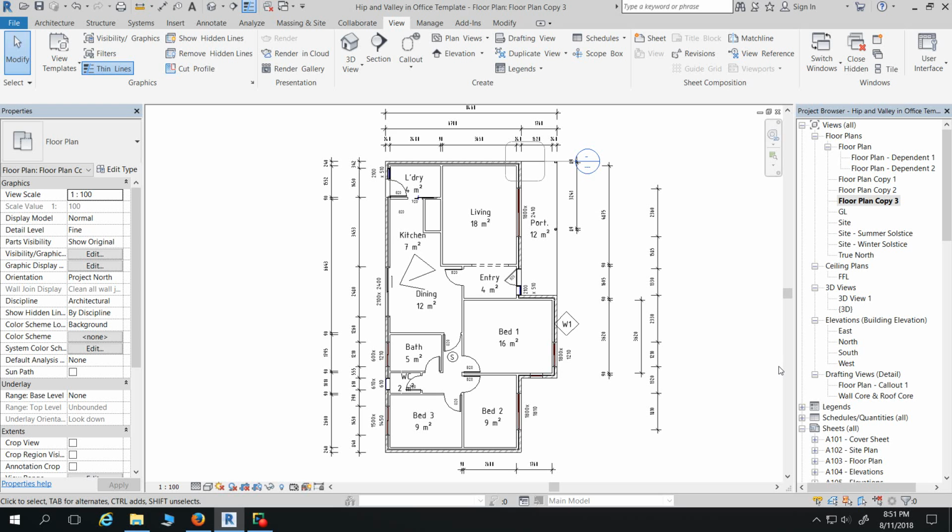Cool. So if you imagine, let's say this is my section of the building. I've taken my overhead projector overlay and I've scribbled on that. So if the building moves, the overhead projector overlay doesn't go with it. It's the same here for the annotation, like the views. So that's duplicating views and the different types. Now obviously, I'll show you how to put stuff on sheets next week. A view can only be on a sheet once. That's why you need to have heaps of different view types, or the same view heaps of times, to put them on multiple sheets if you want.